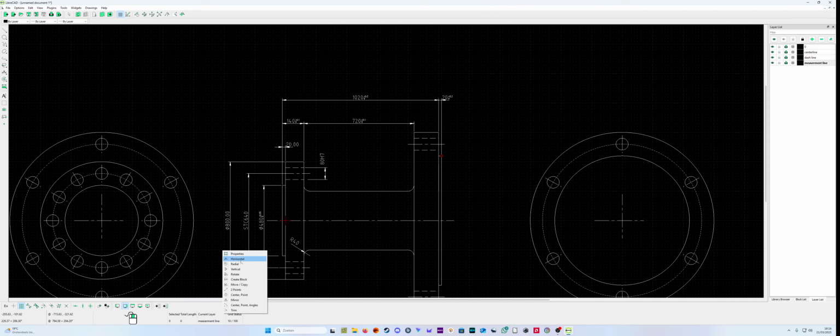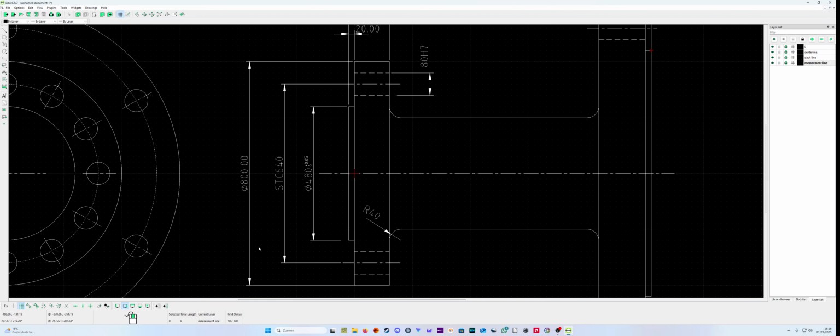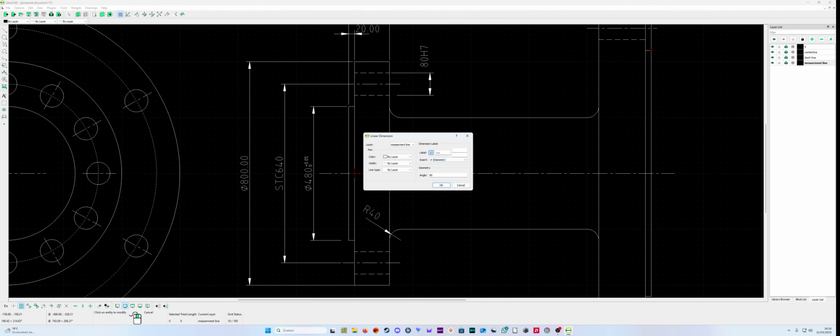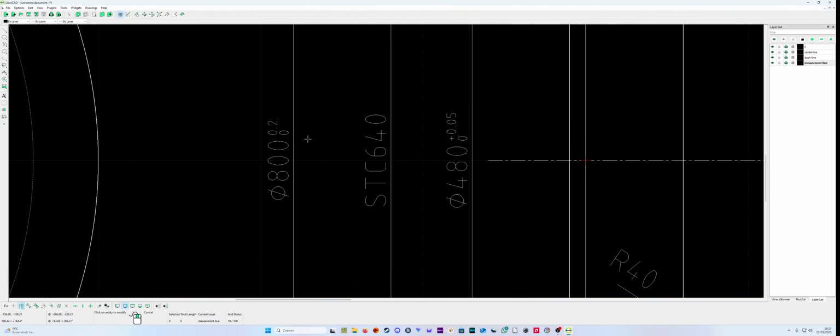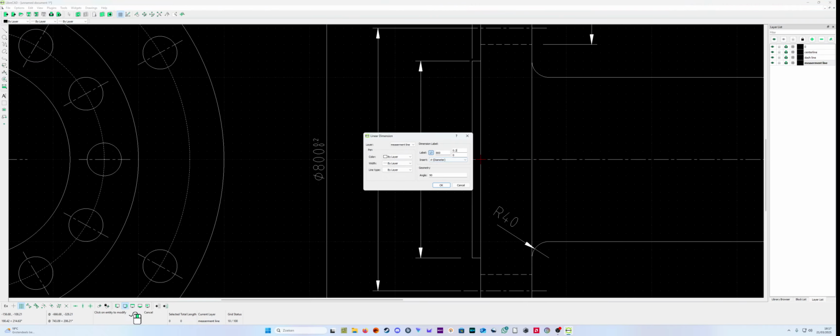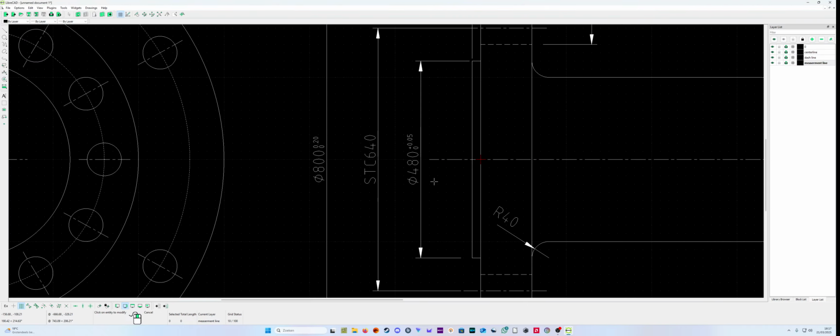Also here you can always put some tolerance inside, because 80.00 is no tolerance, you know what I mean? So properties, and it goes from 80. Oh, sorry, 80. Just do it correctly. And then you can say 0.02 or 0.03. Yeah, like that. Put some tolerance between it. You can also say 0.20 to be exact.